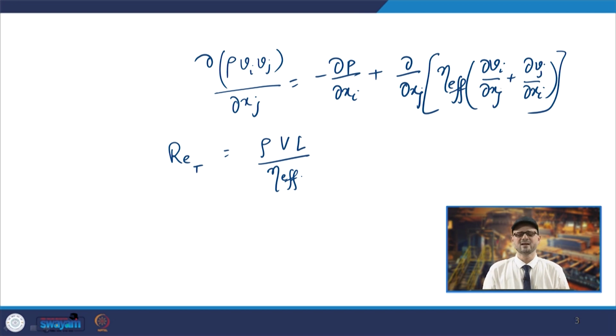and for maintaining that similarity between two Tundishes which have the turbulent flows, you will have to see that there must be similarity. Each term in the dimensionless form should have the same value in both the systems. So, in the model as well as in the actual system, each term must be same, and